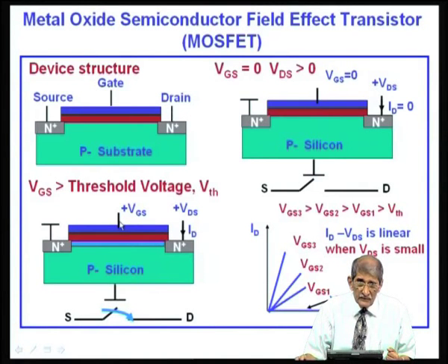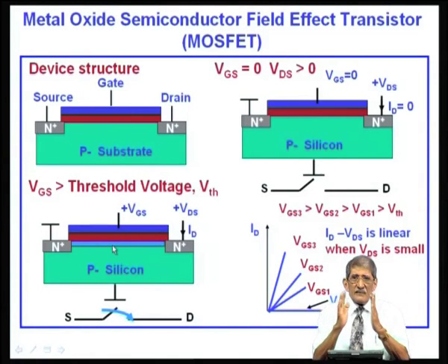So, when I apply voltage to this, plus charges are induced on the gate, minus charges are induced on the other side of the oxide, and these minus charges are electrons. So, when I apply plus voltage, electrons are induced due to the field lines from the gate to the channel, that is the field effect. When I apply voltage between the gate and the substrate, that field effect induces negative charges. It is like a parallel plate capacitor.